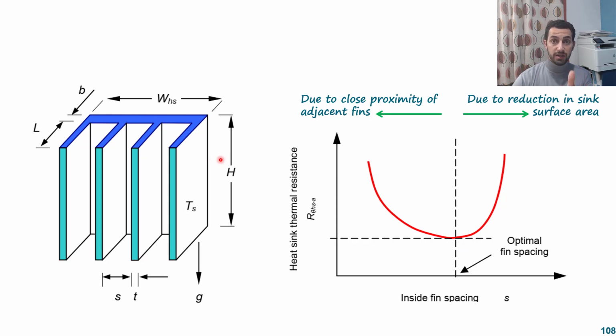and they finally bring to you the curves that we have seen in the previous slide to decide what the thermal resistance is for any power dissipation or for any air velocity. And that brings me to the end of this slide, before covering some examples in the next video for how we use that electrical model to calculate the junction temperature and case temperature or other things, or use it for the design as well, and to decide whether we need a heatsink or a fan or not.